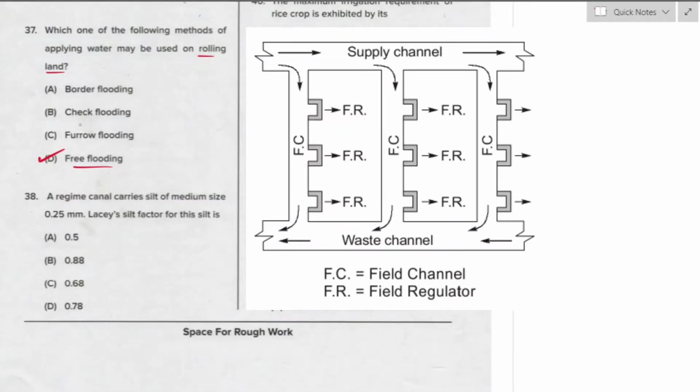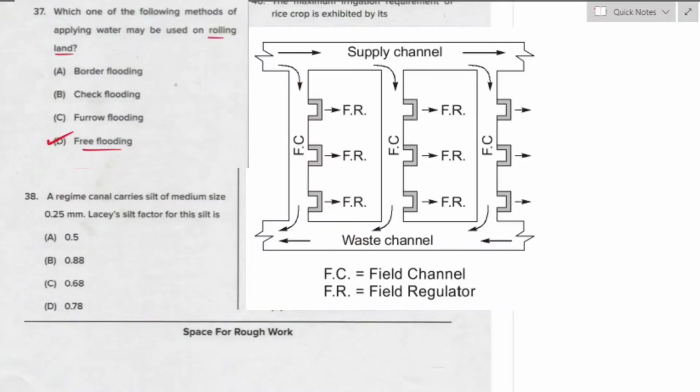where this technique is suitable for sloping land and crops like pastures. In this method, contour ditches called subsidiary ditches are made and are generally spaced about 20 to 50 meters apart. And in this method, the water application efficiency is very low.